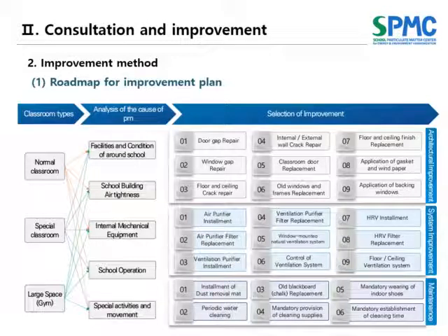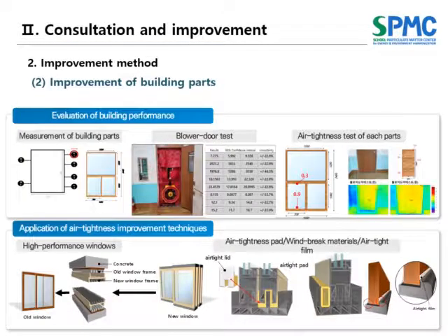The improvement project is divided into 3 categories: architectural improvement, mechanical system improvement, and maintenance. One of the most essential architectural improvements is to improve the air tightness. In Korea, the outdoor particle concentration is often high due to various problems. Therefore, in this study, the priority is to supplement the air tightness to minimize the effect of the outdoor particle concentration on indoor spaces.